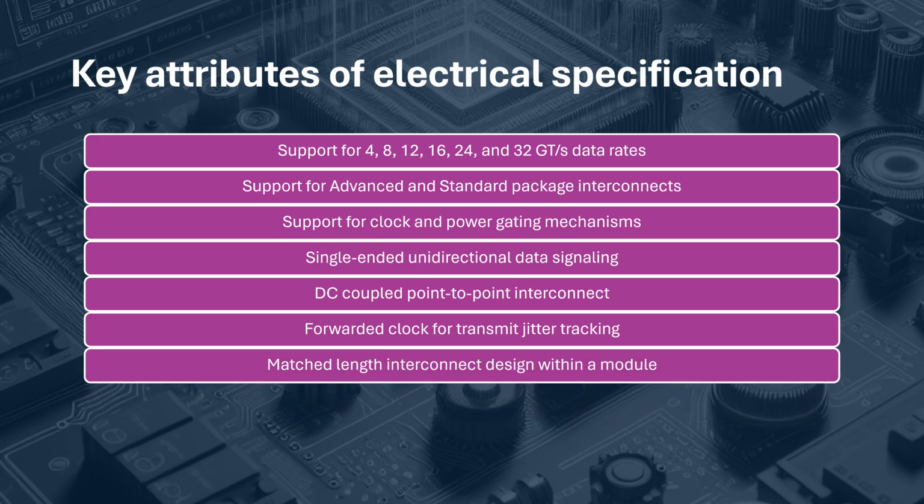Matched length interconnect design within a module. The interconnects need to be matched because at high frequency, even some femtofarads of capacitance introduces a big change in delay between two consecutive lines, right? Matched length interconnect design.